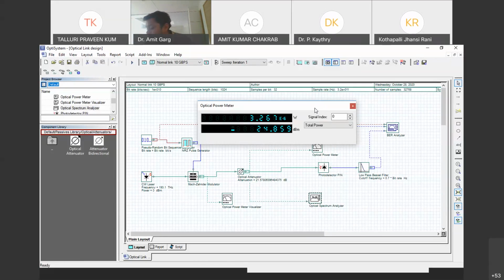So when there is an optical fiber of 85 or 86 kilometer length, then the receiver must require at least minus 20.418 dBm of power to give Q factor 6. And if we are not having any fiber, I'm just directly verifying this link for back-to-back condition.